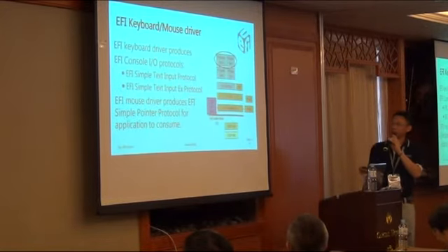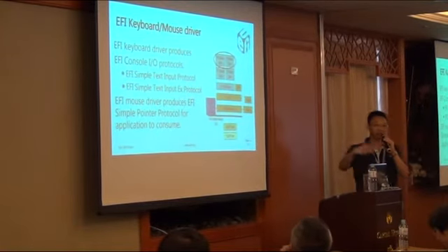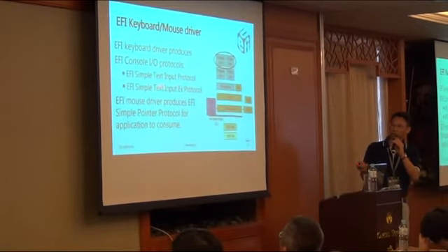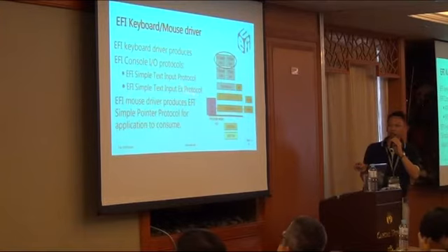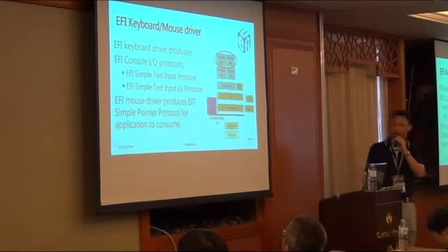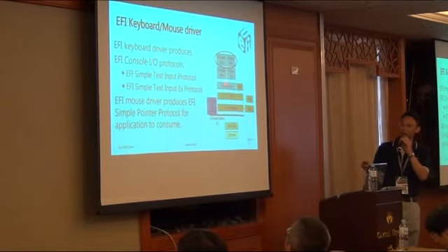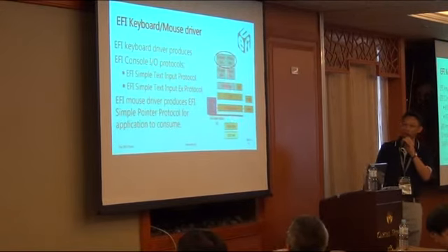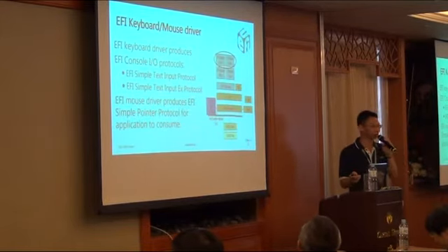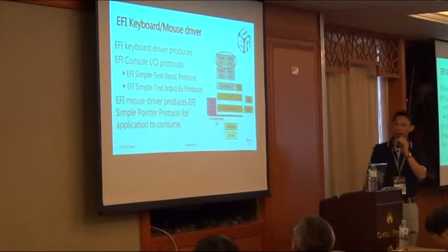Okay, so the UEFI keyboard mouse driver is the main driver which interacts with the UEFI application. For the keyboard, as we know, you need to expose the Simple Text Input protocol and also the Simple Text Input Ex protocol. So a UEFI application can consume this protocol to get a keystroke. This is how you get a Bluetooth keyboard keystroke. And for the mouse, it will produce the UEFI Simple Pointer protocol. This is also a standard protocol defined in the UEFI spec for pointing devices.